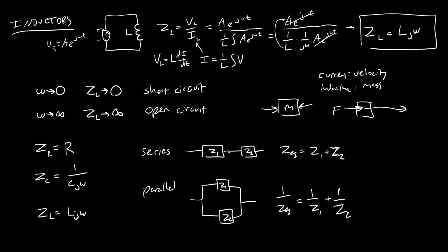The difference here being that before we just did this for resistors, this now applies whether either one of these parts is a resistor, a capacitor, or an inductor. So you can mix them. You can have a resistor in series with a capacitor. You can have an inductor in parallel with a capacitor, or all three in parallel with a resistor, and so on. And you can solve for the equivalent impedance of this combined circuit with different elements.